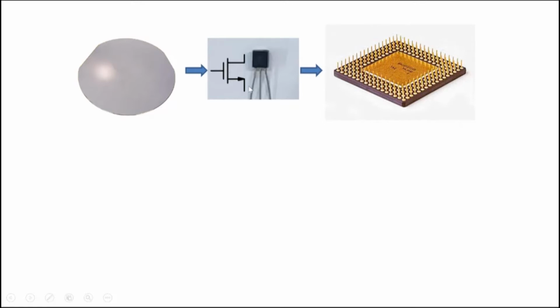All right, so from sand we have obtained a thin slice of silicon. Note that it is pure crystal and the purity level is extremely high. It's one of the purest materials that you can get anywhere on the planet. And so on this wafer is where we make our transistors. A MOSFET that we have seen earlier. On this wafer we can make MOSFETs, and we'll see towards the end of the lecture very quickly how something like that can be made here. And we make not just one MOSFET, but hundreds of thousands or millions or even billions of transistors.